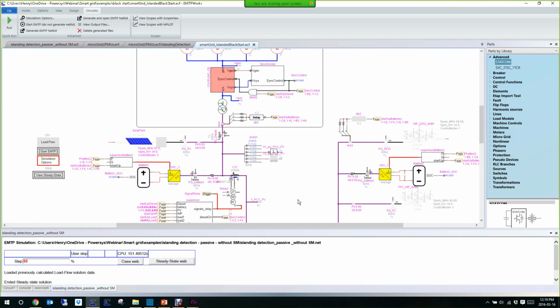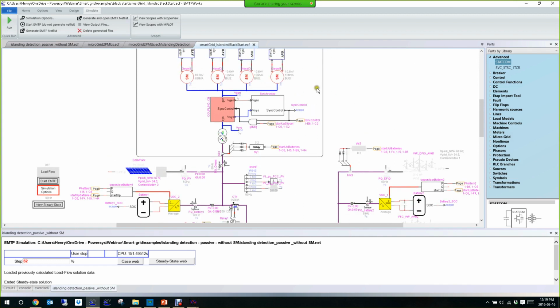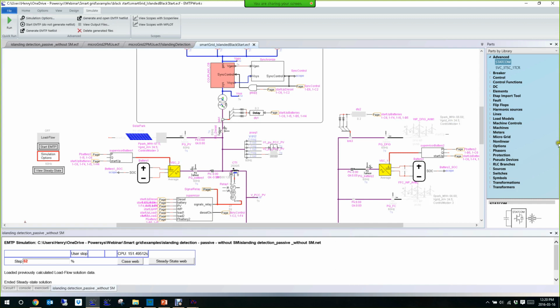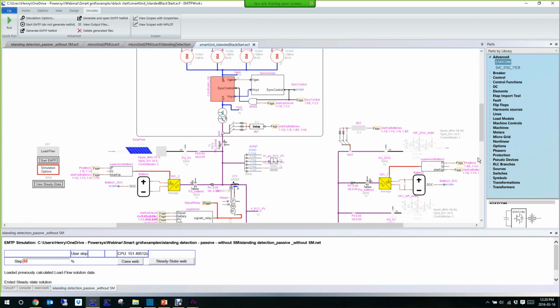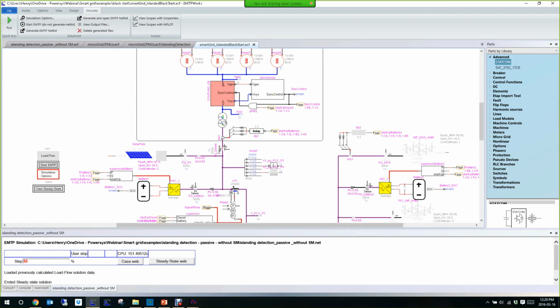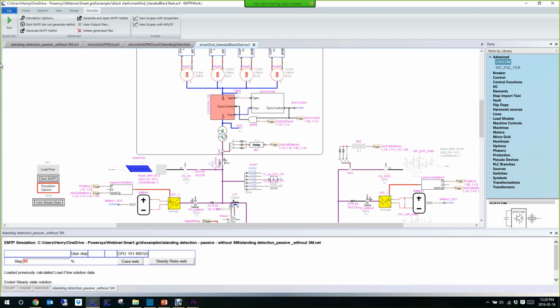Because it can sometimes be a challenge when you have synchronous machines that interact with inverter controllers, because they don't have the same speed, and we can play a little bit with this case. If we put in some different wind park, you will see that you can find some very bad interaction, and you can have subsynchronous resonance of the microgrid, which is very bad because it can damage a lot of the mechanical parts. So one interesting thing to do is to check whether you have subsynchronous resonance when you have some events. You can see them pretty fast. You can apply a fault, for example, and clear the fault, and then see if you have some subsynchronous resonance or how the whole grid reacts.